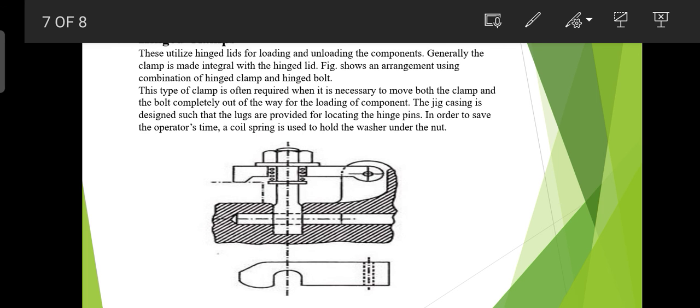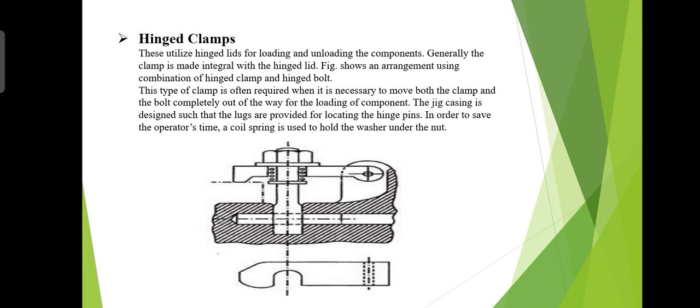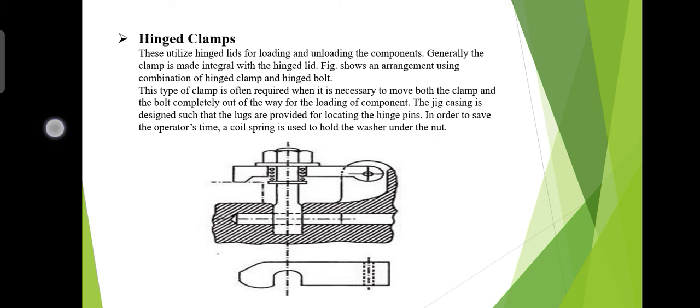locking nut is unscrewed by giving it about one turn, thus releasing the C clamp. In these clamps, once the clamp is removed or swung away, the component can pass freely over the nut, and the release process is adopted to load the workpiece. And thank you. If you have any problem, you can ask. These are the basic